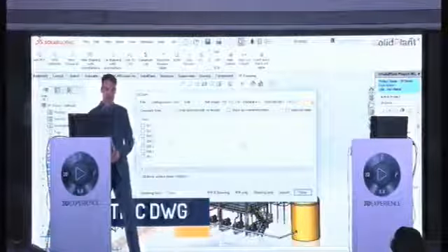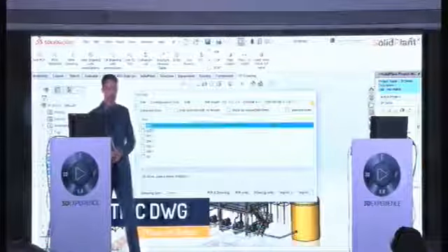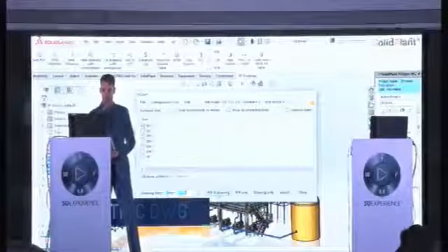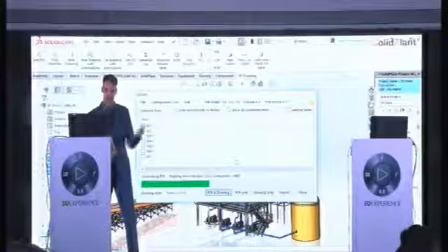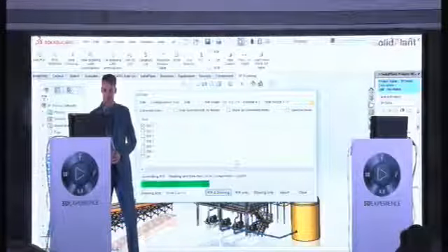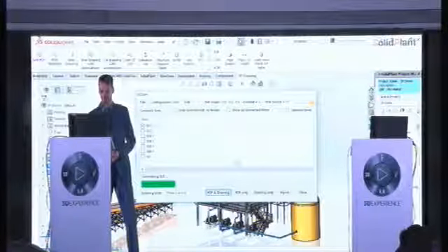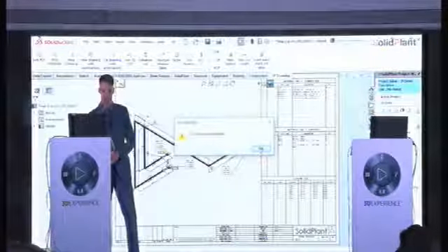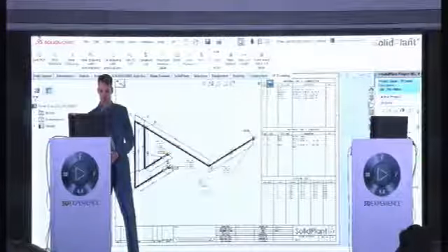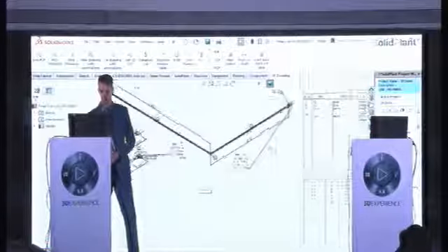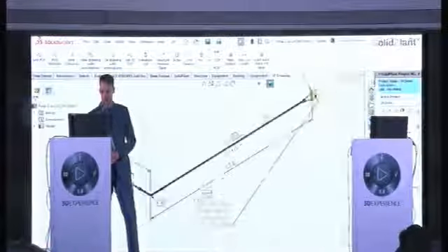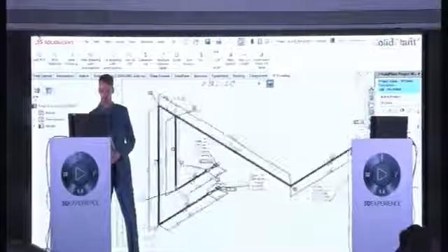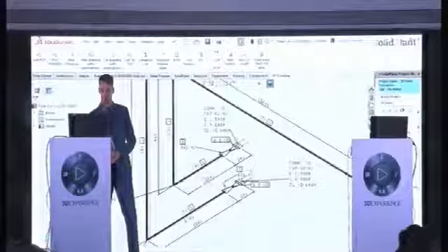Another one is the isometric drawings, perhaps the most important document in plant design. We have discovered, like I said before, by Alias. Alias is the engine for this drawing. For this isometric, it's called IsoGen. So there, it's generated within moments. So it will have all your information about this segment of pipe right there. All the dimensions, all the tag numbers, everything is there.